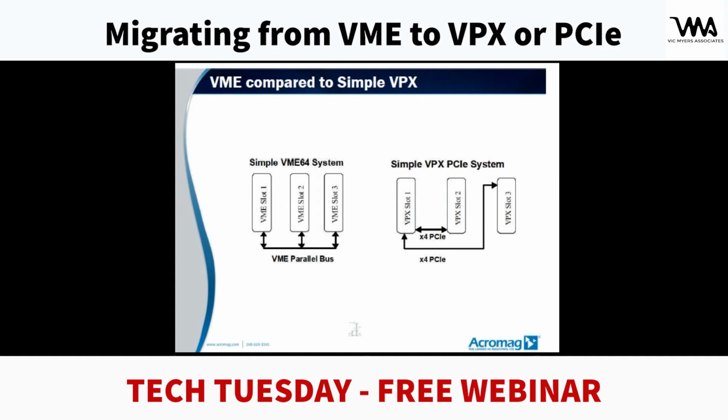And the board in slot 1 has an interface, what we call a by-4, which is a fat pipe interface to the board in slot 2, and it also has an interface to the board in slot 3. But for the board in slot 2 to talk to slot 3 would have to go through slot 1. So it gets kind of cumbersome once you start expanding with multiple boards.